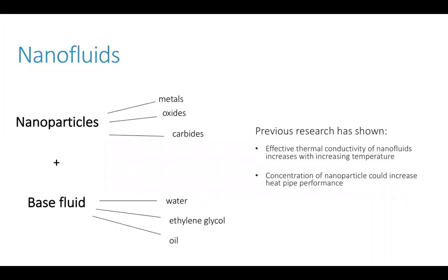So essentially what nanofluids are is that they consist of nanometer-sized particles known as nanoparticles, and they're combined with the base fluid. The nanoparticles tend to be either metals, oxides, or carbides, while the base fluid is usually water, ethylene glycol, or oil.